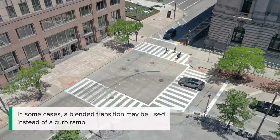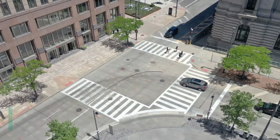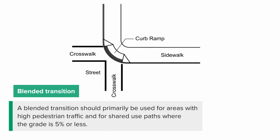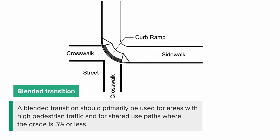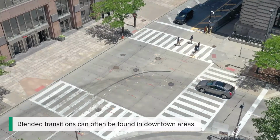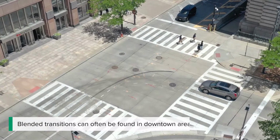In some cases, a blended transition may be used instead of a curb ramp. A blended transition should primarily be used for areas with high pedestrian traffic and for shared use paths where the grade is 5% or less. Blended transitions can often be found in downtown areas.